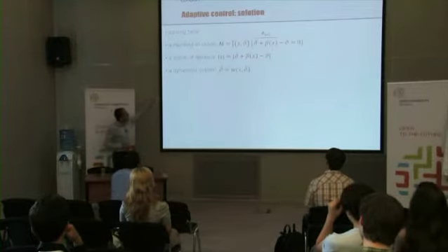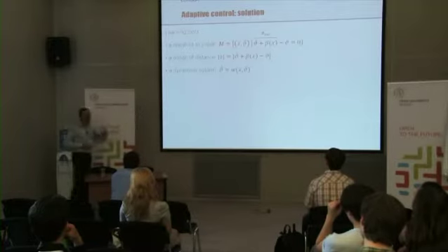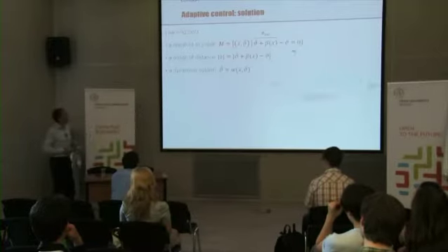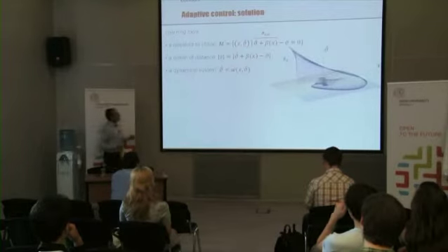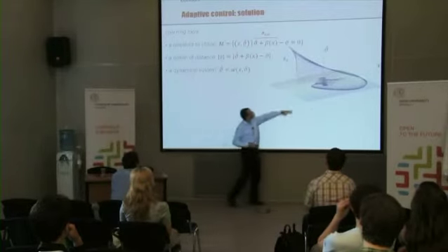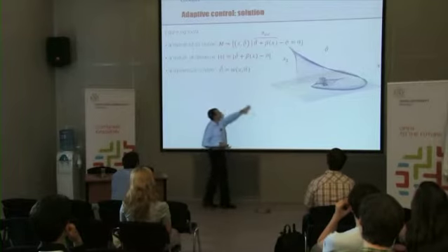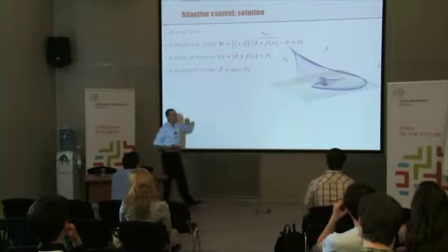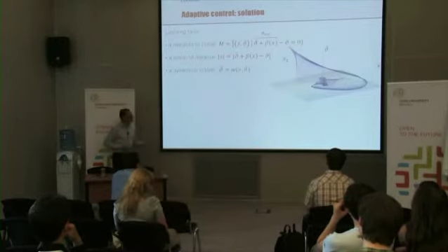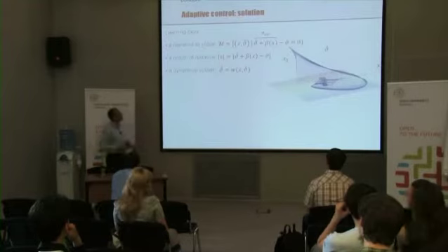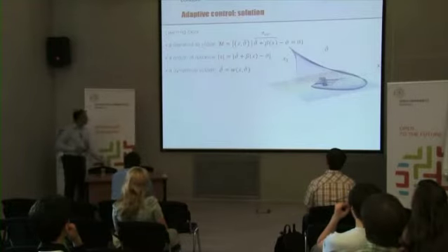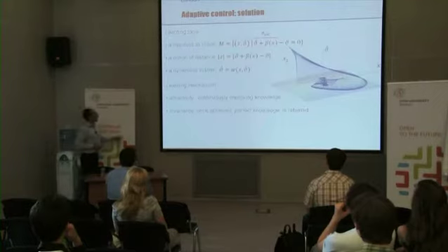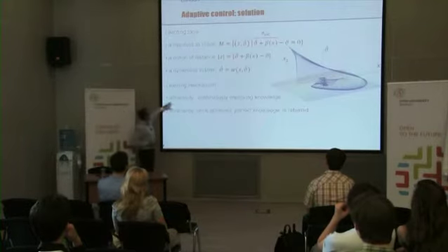Now, once I know how far away, I have to decide how theta hat is changed, because theta hat is my guess for the new decision. Okay, so the idea is that this surface is the ideal surface. If I'm here, I know everything, but actually I'm not there. But I would like all trajectories to move towards this ideal situation. I would like to learn as much as possible with time to go close to a situation where I know precisely what happens. So the learning mechanism in a mathematical perspective is described as attractivity of this set.